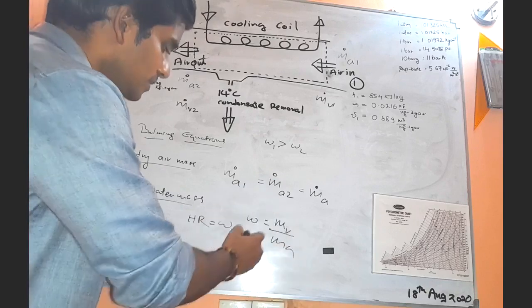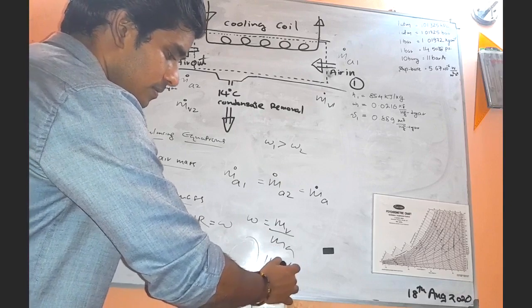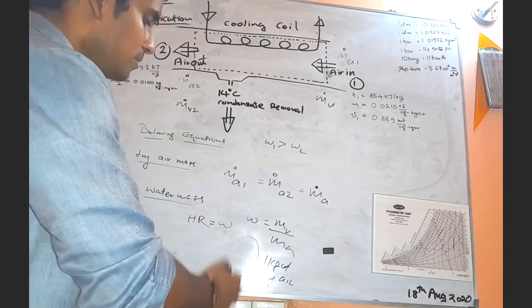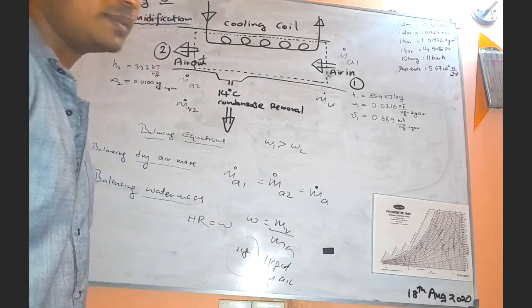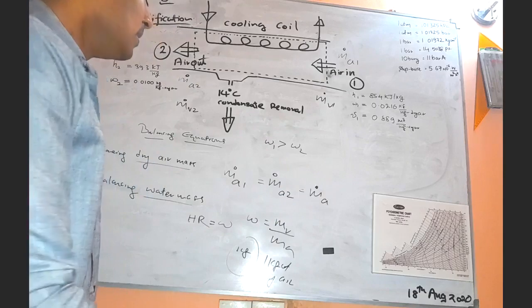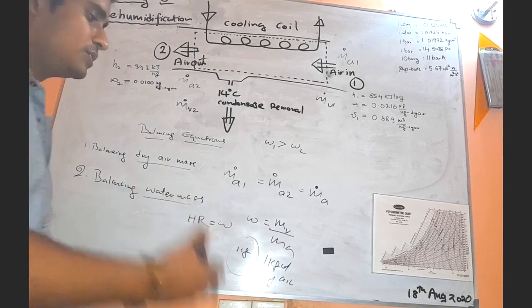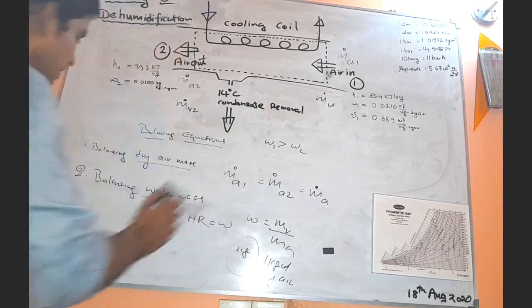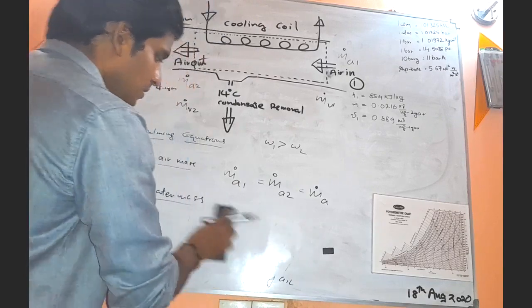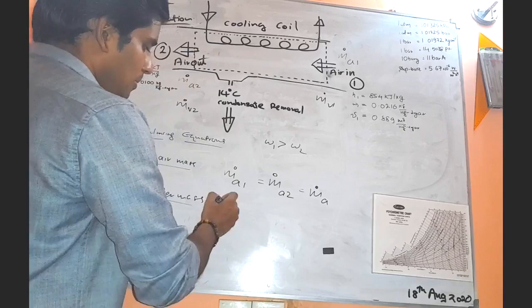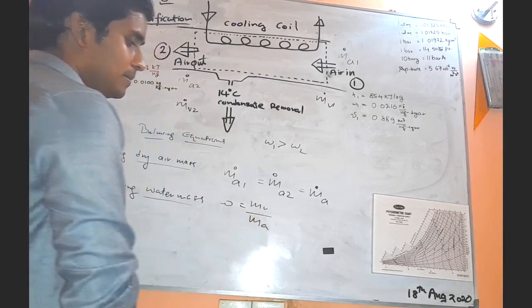That means if you are going to consider 1 kilogram of dry air, what is the amount of water vapor that is present in kilograms? Very important, be very careful about the units. Now for that we can write a very clear equation, when considering the balancing of water mass. I will write it again. So now we know that omega equals mv divided by ma. Got it?